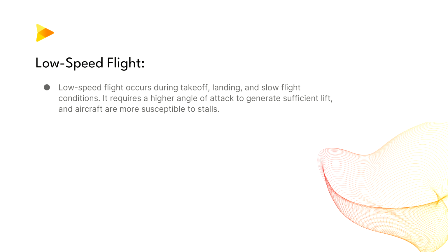So next, low speed flight. It occurs during takeoff, landing, and slow flight conditions. It requires a higher angle of attack to generate sufficient lift, and aircraft are more susceptible to stalls in low speed flight. So for you to maintain level flight, you should raise the angle of attack while equating to the weight of the aircraft.